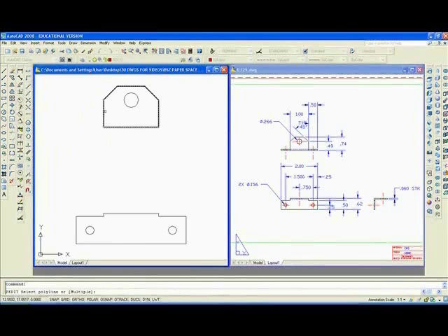You can see if I hover over it, it's one continuous line. Do the same with the bottom. Going to type PE enter, select a line, make it a polyline, yes. J enter, select those lines and these, enter. Might be a good idea to move the two pieces closer together.